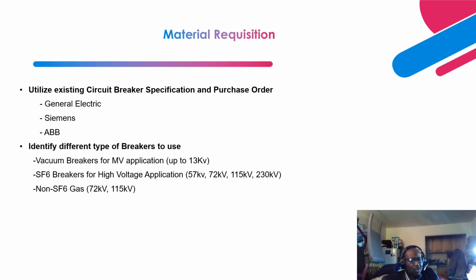Then, as you know, most nations, and in the United States certain states, are pushing for non-SF6 alternative gas circuit breakers. California, for instance, as a means of net carbon reduction, carbon zero, is pushing that by the year 2030 no utility should have an SF6 breaker in place. And some of the states have also started.